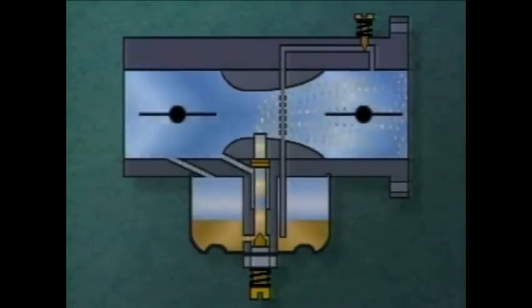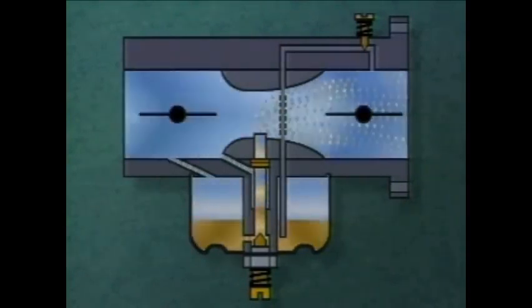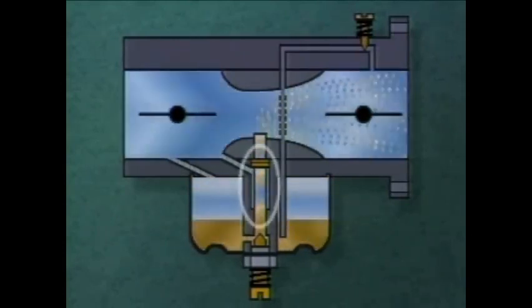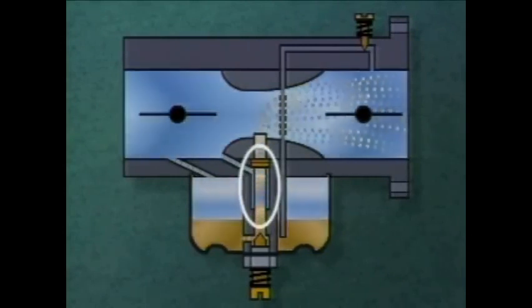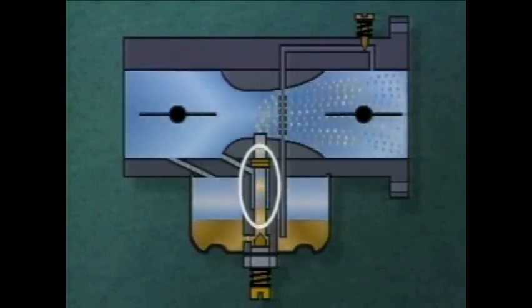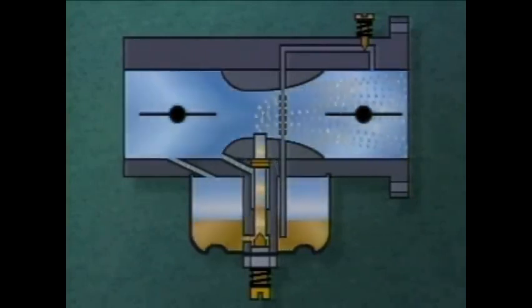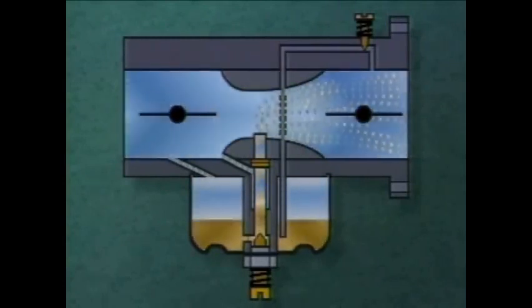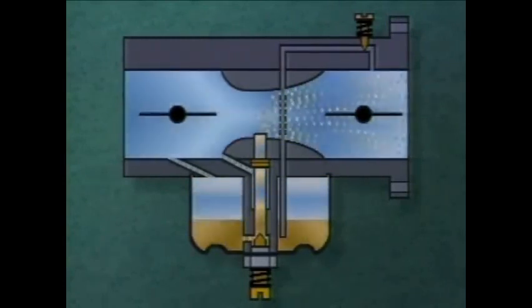Now, when the pressure differences are created between the venturi and the air pressure in the bowl of the carburetor, not only will fuel be pushed up the high-speed pickup tube, but a metered amount of air will be entering the pickup tube at the same time. This starts to break up and atomize or vaporize the fuel before it even enters the carburetor's venturi, as well as offering low-pressure relief under no-load conditions.